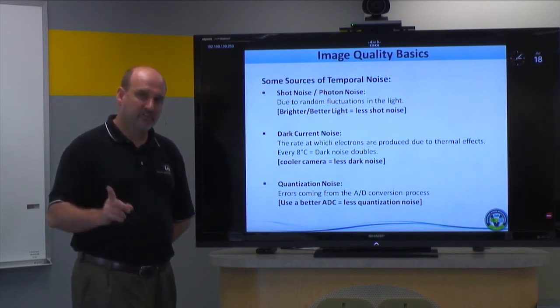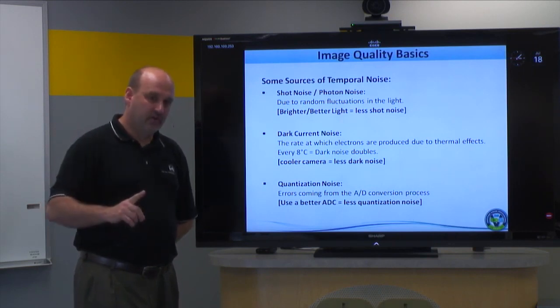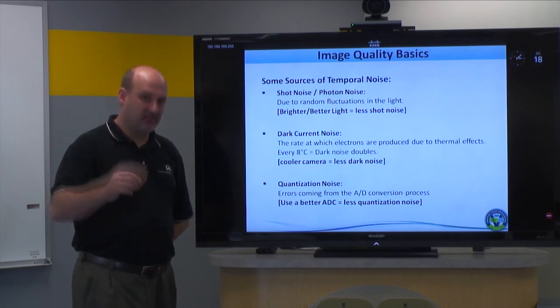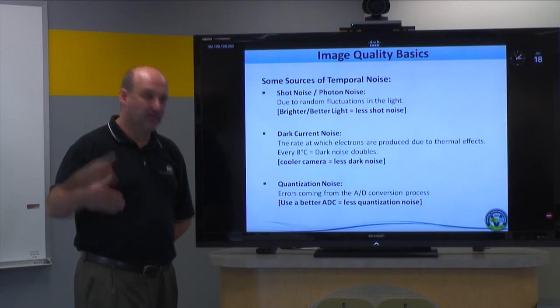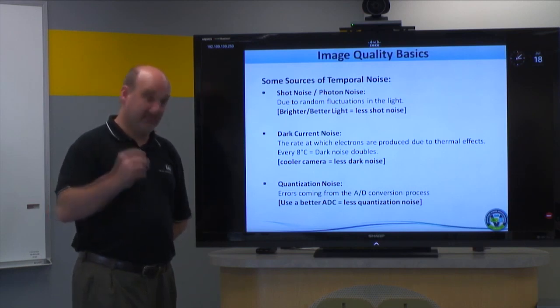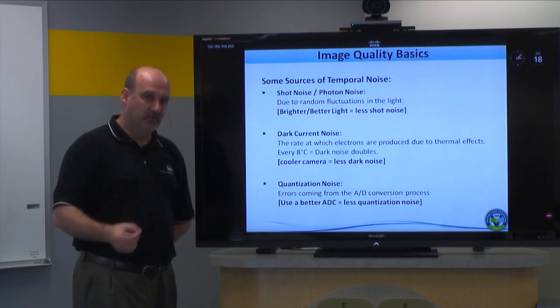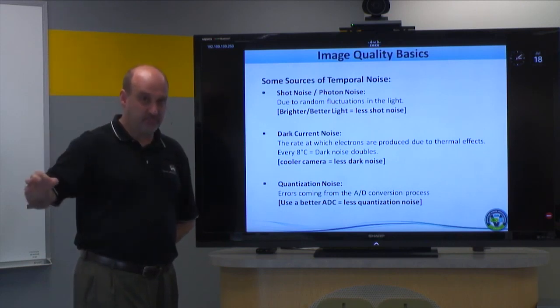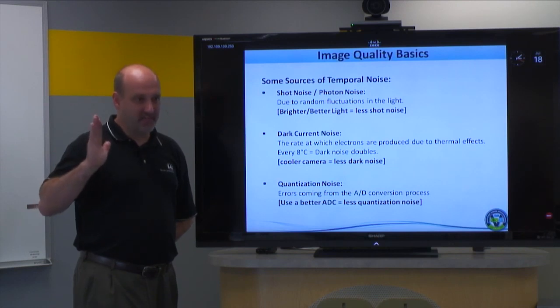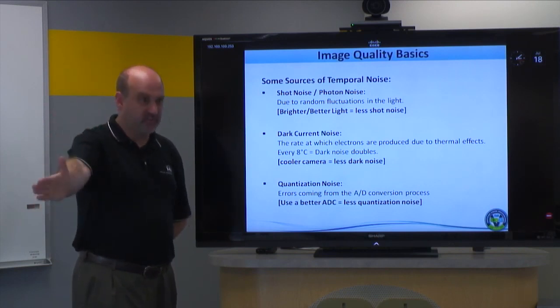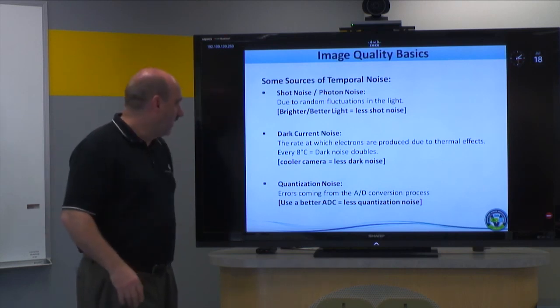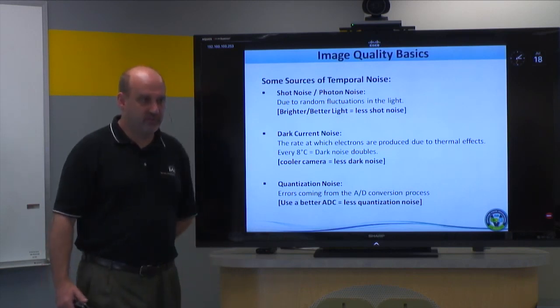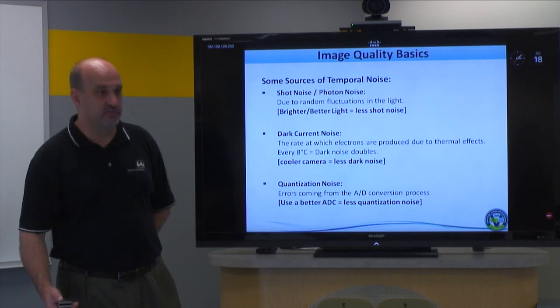This is fundamentally important because, as I just told you, in a CMOS camera, the A to D converter is built on the chip. Not only that, there are massively parallel ones on the chip to read out all these pixels, which is fundamentally why they're faster. However, by the nature of that, they have to keep the structure very simple and very small to fit at the pixel level or at the column level, and therefore the on-chip A to D converters on a CMOS imager are nowhere near on par with an off-chip discrete A to D converter we can build in a CCD camera. Plus, in a CCD camera, there's only one stream running through that one A to D converter, so there's no variation from A to D converters. So quantization noise is a big difference between CCD and CMOS cameras. This is also why CMOS cameras tend to be a little noisier than CCDs.